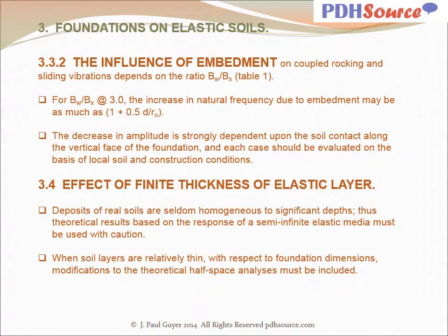With regard to the effect of finite thickness of elastic layer, deposits of real soils are seldom homogeneous to significant depths. Thus, theoretical results based on the response of a semi-infinite elastic media must be used with caution. When soil layers are relatively thin with respect to foundation dimensions, modifications to the theoretical half-space analyses must be included.